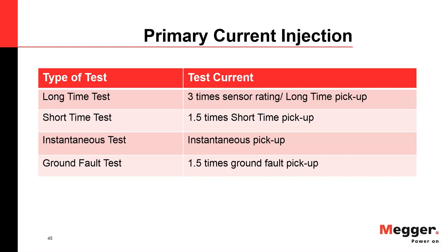There's also a term that is called frame rating. You have to be careful with that. Frame rating means what manufacturers do is they build a certain circuit breaker, a certain module, and then you can equip this circuit breaker with different CTs, with different sensors, and they can have different ratings. So they have one mechanical design to accommodate different electrical duties.